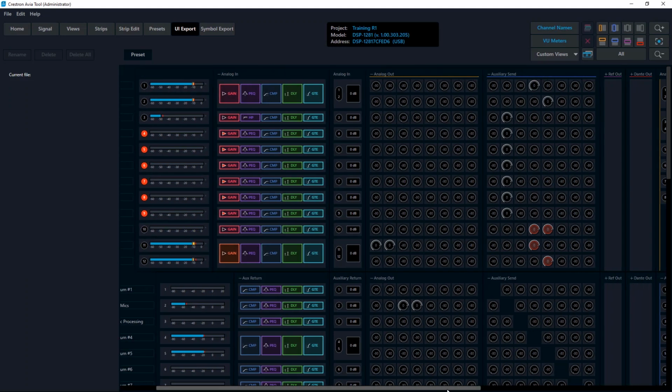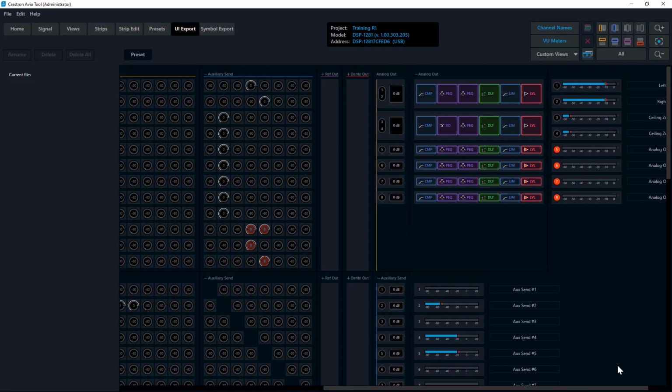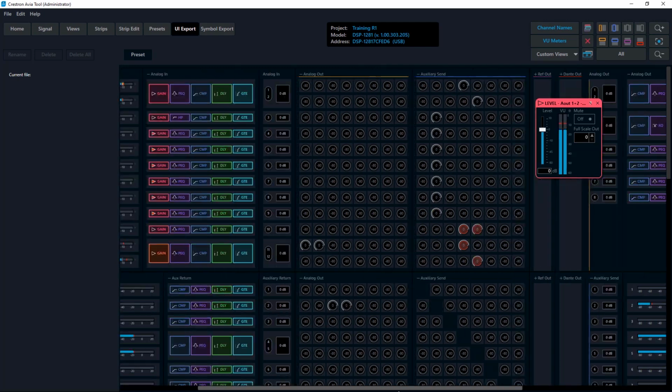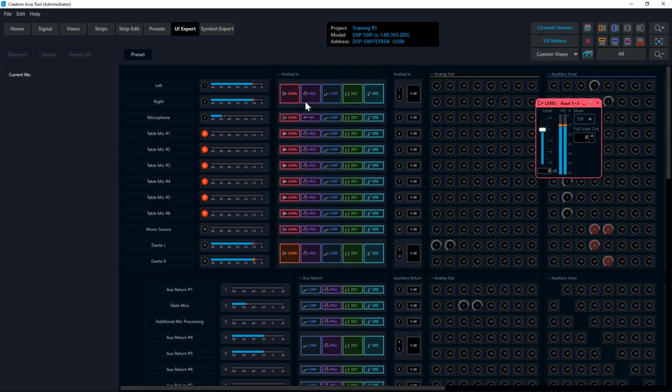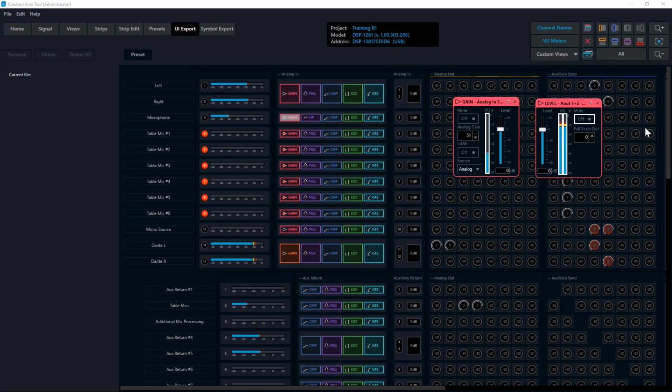First, we will open the objects with the data points we would like on the touch panel. Note that items inside objects along with the objects in the matrix can be selected. To select objects, control-click the objects. They will have a bright white outline around what has been selected. I've selected the VU meter for the mic input so the client can confirm the mic is picking up signal. With the control key still held, click and drag one of the objects over to the palette area.